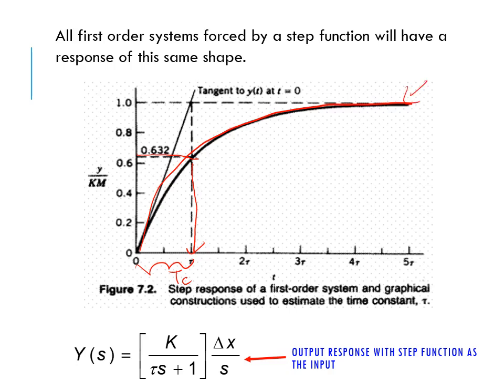And to obtain the step response of magnitude delta x, we transform the input X(s) from the general transfer function of the first order differential equation. We replace X(s) equals delta x divided by s. Alright, we change X(s) into delta x over s.